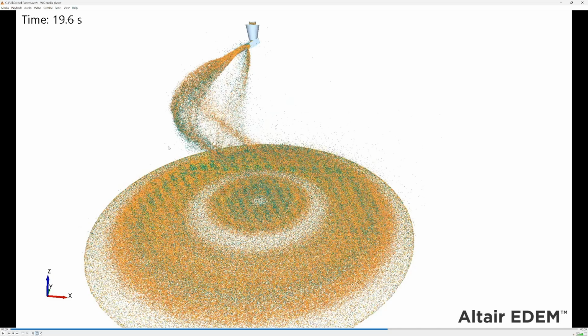And what you'll see is these cyan-colored fines, these smaller particles, are being carried out away from the center of the bin. So the way our spreader works is we have a couple of fins on the fan board. We have the first fin right here we call our redirect. So it actually takes some of the grain that's moving down and out, and it reverses the flow back to the center. We don't just punch a hole in the middle of the spreader and let grain pile up in the center. We actually reverse the flow and spread it back onto the center of the floor.